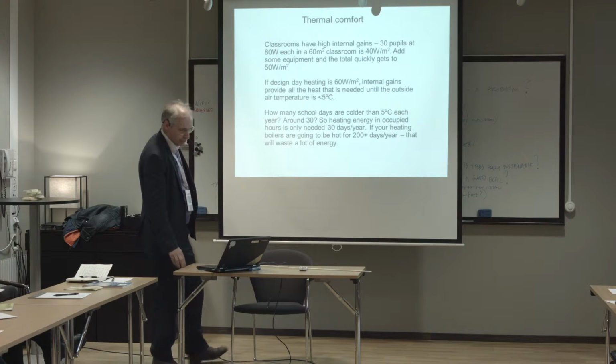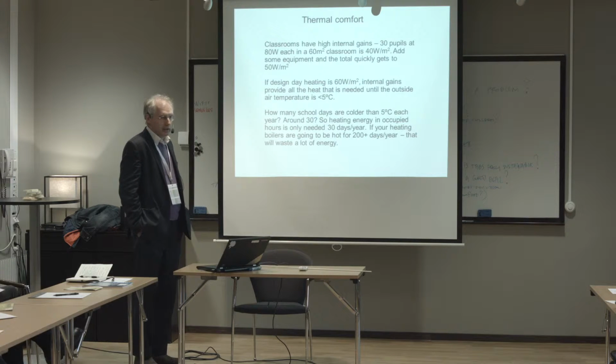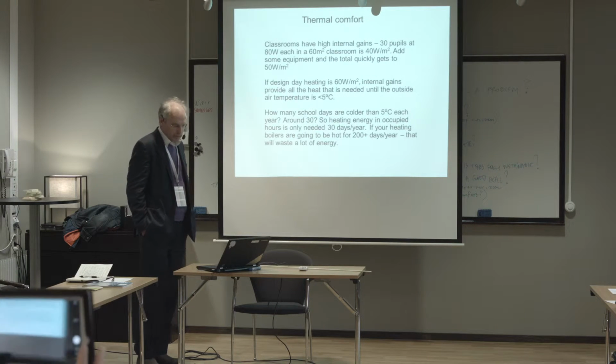We've got a very simple line plume calculator that's been developed in England, which estimates the cold dumping effect from different height openings at early design stage. So we can tell what height the openings have to be to give certain litres per second for the pupils.